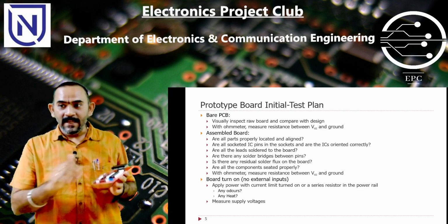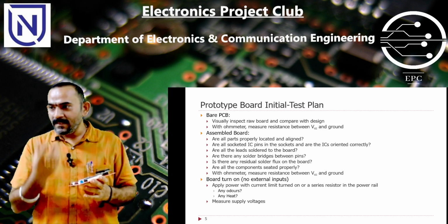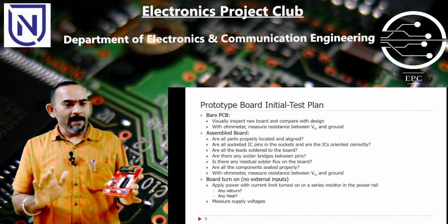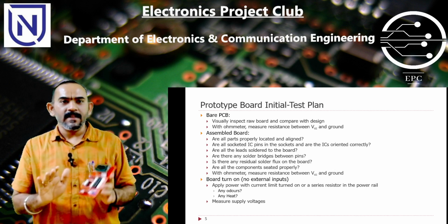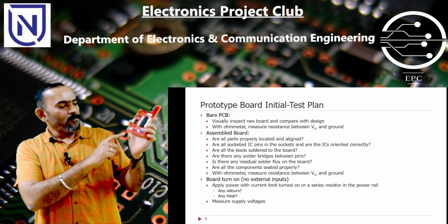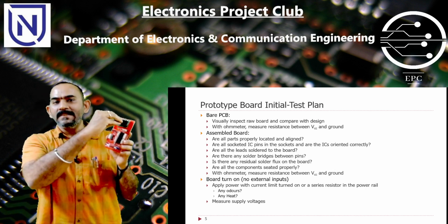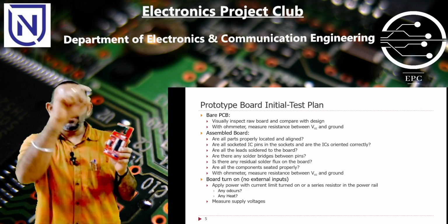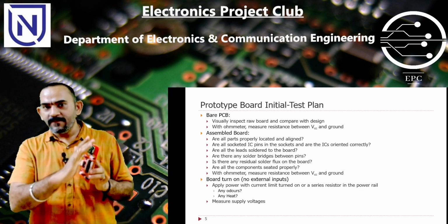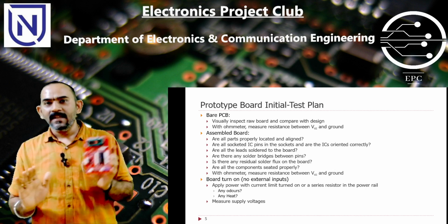Both temperature also will increase, board temperature will also increase, as well as if there is any fault you will also get the smell. Okay, so both these should be checked. And if nothing happens, maybe 10 to 15 minutes you keep it, finally everything is fine, you then measure the voltage. Assume for this board the voltage should be 5 volts, and now I use a regulator here to generate some intermediate voltages. I measure all those voltages, see that it is as per the design specification. So if this much is done, your first job is done, as a hardware engineer.